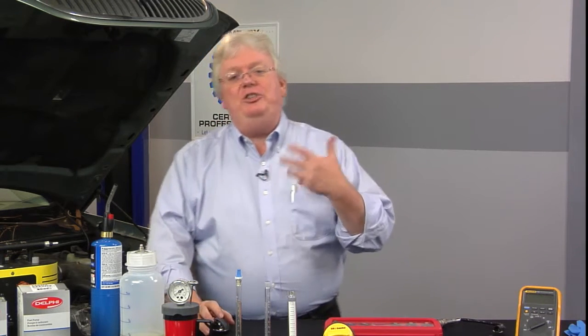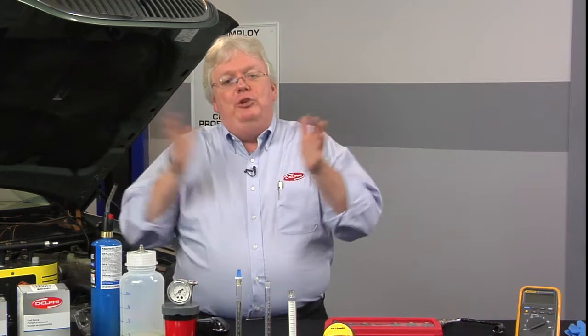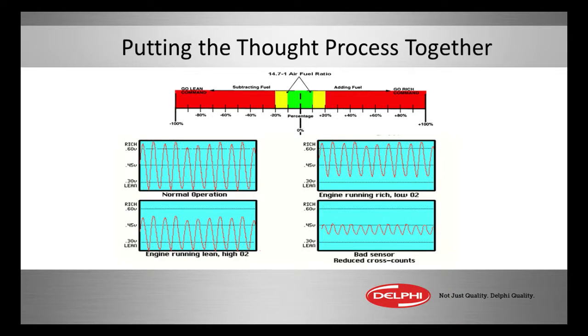Now, as we move all this together, the graph that showed fuel trim acceptability, borderline in yellow, and then red should set a code, and how it corresponds to the actual O2 values. If we graph or scope an O2 sensor of the traditional switching design, as we see it go full rich and full lean, not hanging out either one of those two places, a good switching time, we see it in the green, 0 to 10 either way.